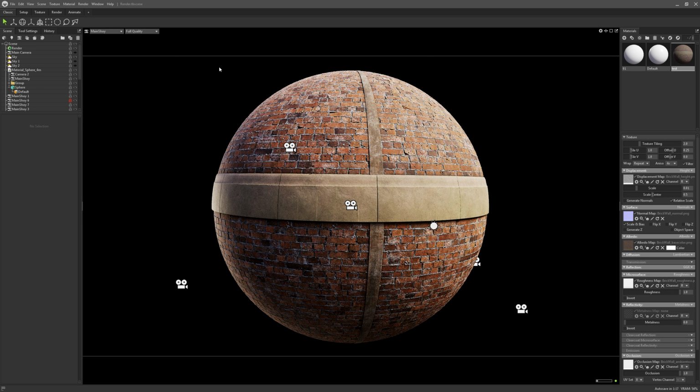Another thing I'm realizing is that my displacement is not working really well, and we are going to talk about that really soon. But first I'm going to change my height scale to 0.02. This is going to allow me to have more height, and also better shadows, as you can see down here. How we work with displacement is something that comes in Marmoset Toolbag 4, and different to Marmoset Toolbag 3, it comes specifically with the mesh. That's going to be the next step. But first, let's talk about the normal and the albedo.